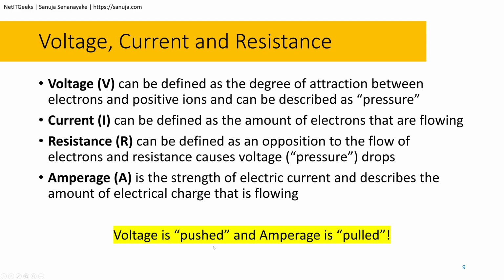Voltage is pushed to the device, amperage is pulled by the device. So it is important that you check the voltage before you plug in any devices, even network devices, because some PoE devices may not have that auto negotiation of the voltage. Okay, keep that in mind.